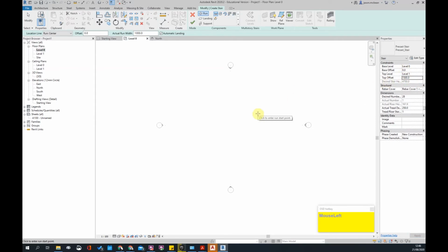So especially if you're coming in, so where this would happen, maybe let's do it this way. So that must be level 0. You could also say this step is going to end on 0, but start minus 1,500. Okay, so let's try this option very quickly. So you're going to say run. Now you've got different types of stairs we can use. I'll get to that in a minute, but let's just pick a straight run. And it'll tell you once the stair's finished, because we've set the height there. So that's how many are remaining.